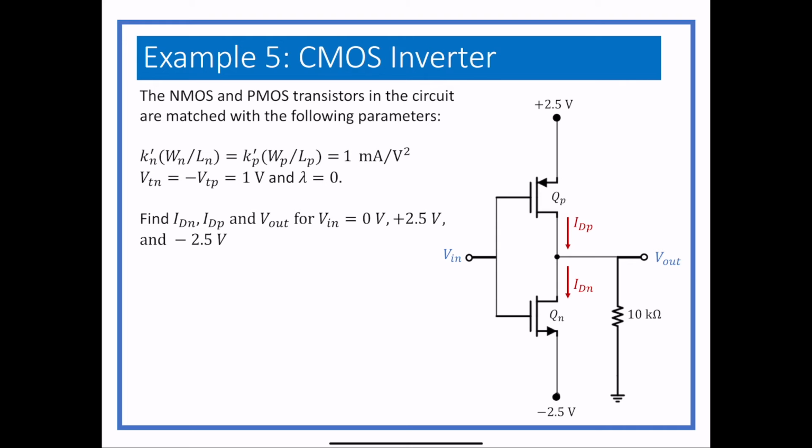So we have two transistors put together. Remember that with a PMOS, the drain and the source are flipped over, so I didn't actually mark them. Sometimes I do. The gate obviously is the same in both areas, and then we have the drain and the source, and this is the drain and this is the source with this one.